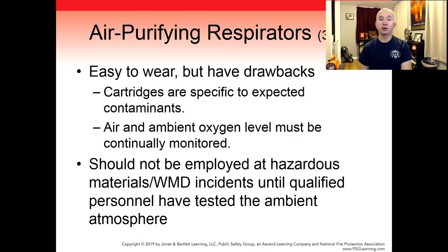APRs are easy to wear but have some drawbacks. Cartridges are specific to expected contaminants and are ineffective if the contaminant suddenly changes. Air must be continuously monitored for the known substances and the ambient oxygen level throughout the incident. APRs should not be employed at hazardous materials incidents until qualified personnel have tested the ambient atmosphere and determined that the devices can be used safely.